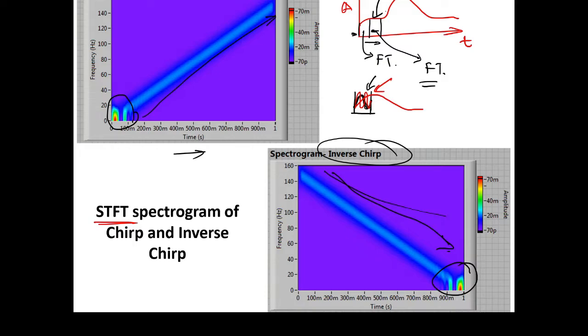So what does that do? That induces aliasing into your analysis, because the window is not capable of analyzing a frequency component, and due to that reason, in STFT at lower frequencies you will be getting some distortions.